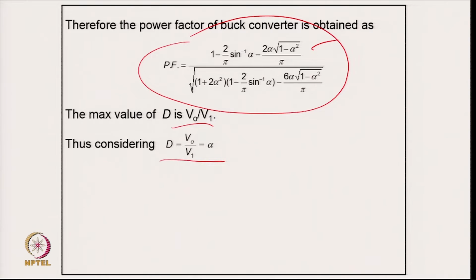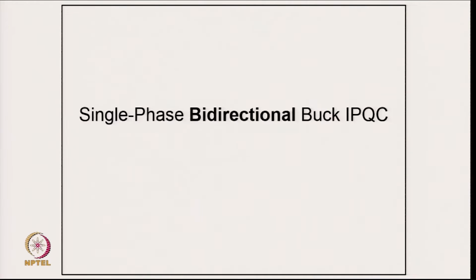So, we consider that you can easily get power factor correction with power control, but of course in DCM you get inherent power factor correction compared to that. So, coming to bidirectional, these were unidirectional. Many applications require unidirectional power flow, like all the power supply applications we mentioned, such as LED lighting. But some applications have a bidirectional power flow also.